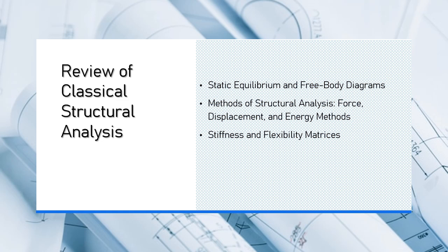Energy methods are often used for analyzing indeterminate structures, especially when other methods are difficult or time-consuming. These methods are useful for calculating deflections, internal forces, and moments in complex structures, especially when the system involves bending, twisting, or other nonlinear behaviors. Example: in the analysis of a cantilever beam with a load, energy methods can be used to calculate the displacement at the free end of the beam by calculating the strain energy and work done by the applied load.